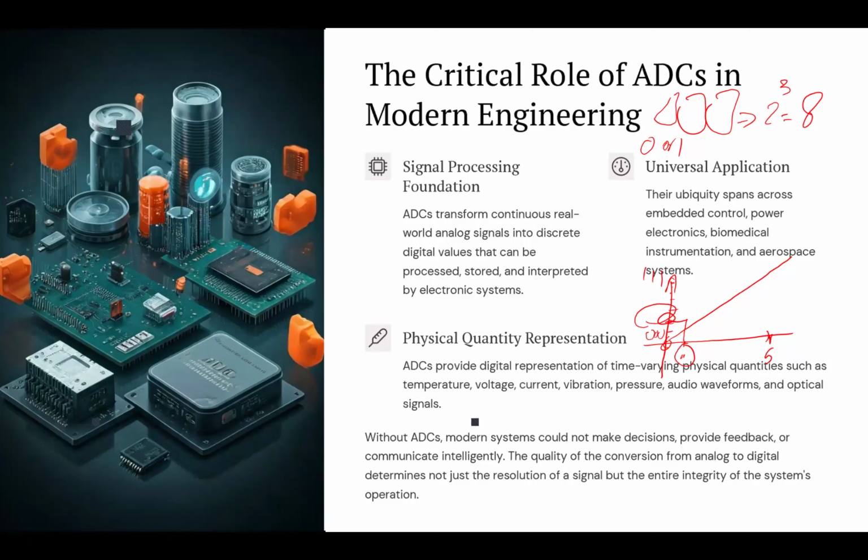Now, if we need an analog signal later on, we could again convert that digital signal using a DAC, digital to analog converter. For example, when you want to display what you measured on an oscilloscope, the measurement would go through the ADC and become digital. Inside the oscilloscope, it processes the digital signal, and when you want to show it on the screen, you need to again convert it from digital to analog so you could show it on the screen. So this is the gist of